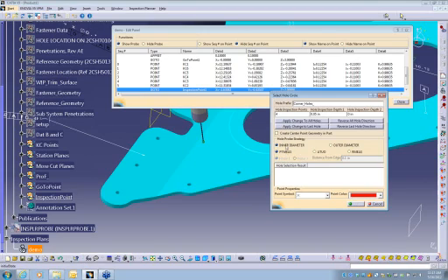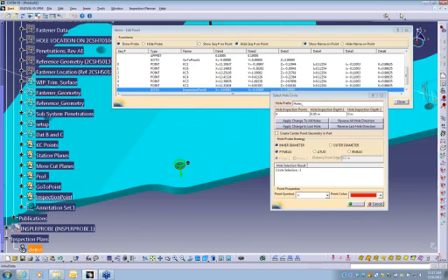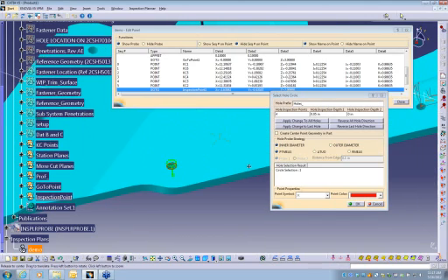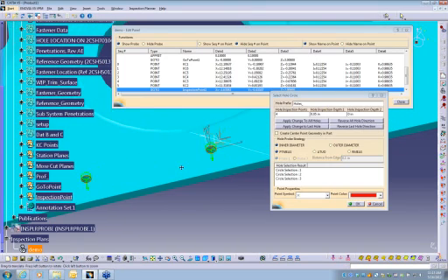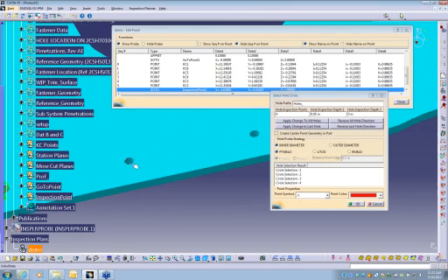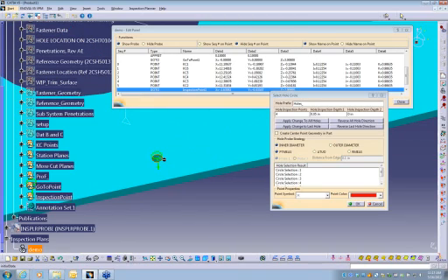So right now we have it set at PT measure. We have an inside hole, not an outside hole, as our hole strategy. We're going to probe 4 hits. We're going to go down 50 thousandths. We're not going to probe it a second time. And we'll just call these holes underscore. So everything is named, and literally all you have to do is just pick the curve. We'll change all the approach and track in one pick. So it's a one pick click.